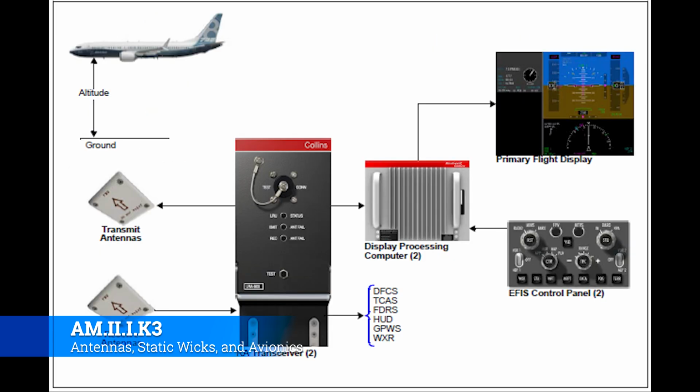These are very unique. So these are the radar altimeter antennas. Notice that they have to be going a certain way. They can't be painted or obstructed in any way. And so you'll walk underneath the airplane, and you'll literally see just this little square white antenna that's buckled up to the airplane. And that's because if anything gets on them, it will mess up the way the radar altimeter operates.